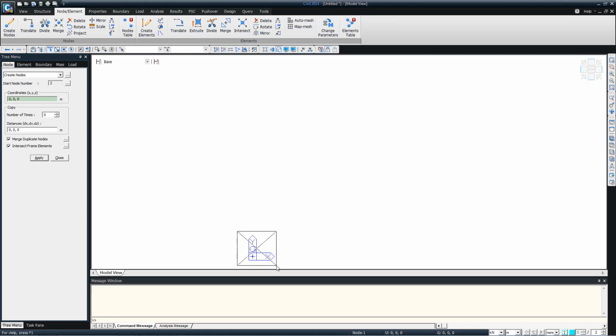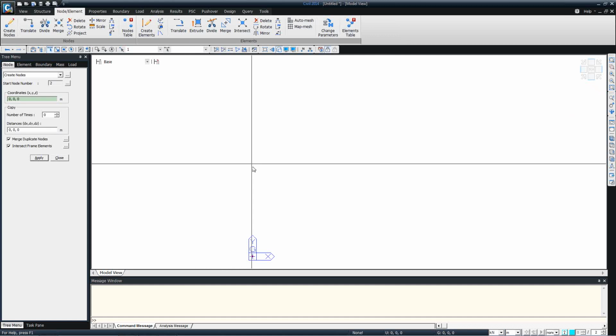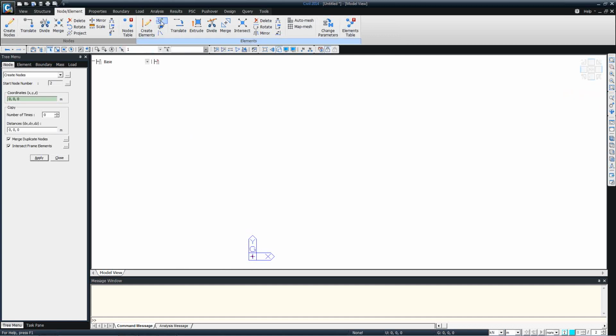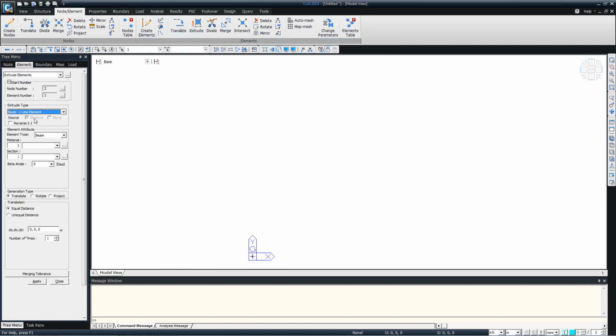So I'll use this node, select it. The selection tools are similar to AutoCAD. So selecting this and extrude, say just enter how many divisions I want on that skew, on that line. So say in the Y direction, say 4 at 3 meters, for example. Apply.